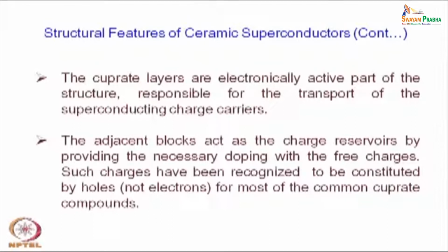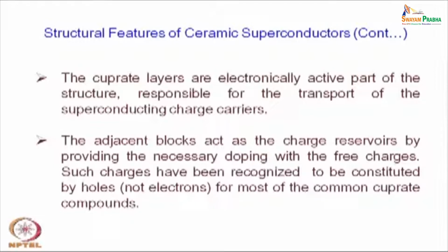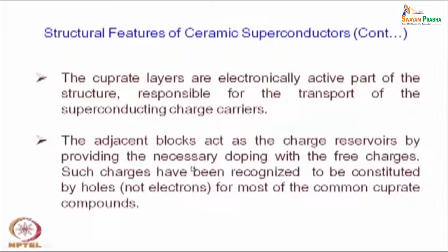Electron pairs move, and those are the charge species which carry the charge or give rise to the conduction process, whereas in case of high temperature superconductors, it is believed that not the electrons, but the holes are the more predominant charge carriers here. So, that is one of the differences between the high temperature superconductors, oxide based or ceramic superconductors, compared to elemental or intermetallic superconductors, which we have discussed earlier.